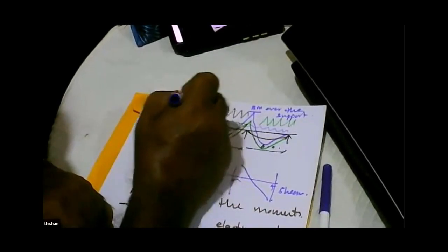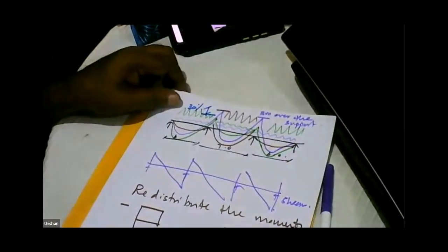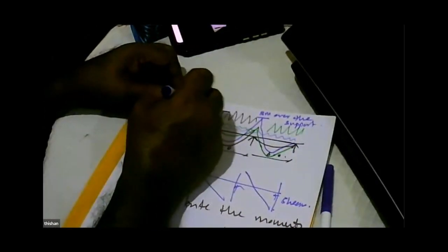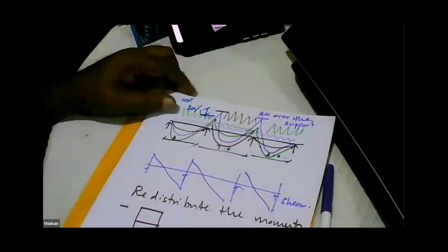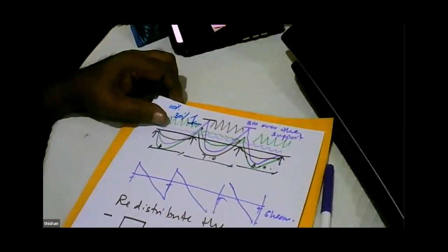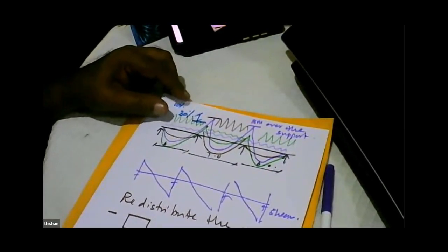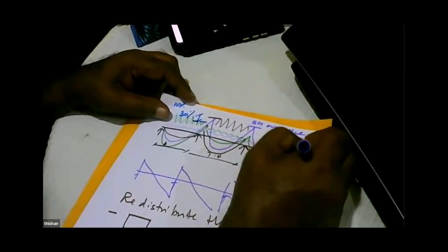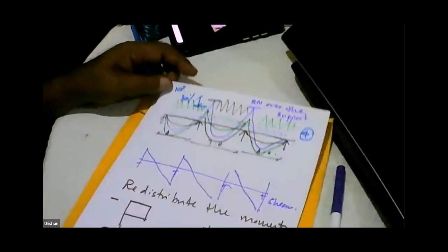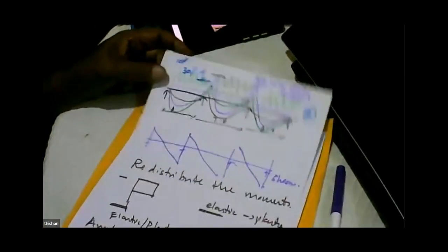You can reduce this moment up to 30%. But I generally prefer about 10%. Easy. Otherwise, when it is more than 10%, you have to do extra. You cannot use the normal equation. You have to modify the design equation. So I generally prefer 10%.